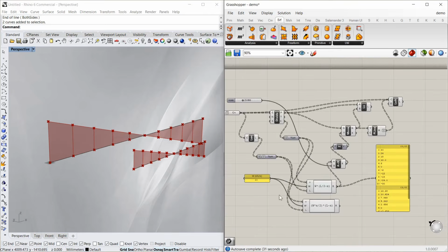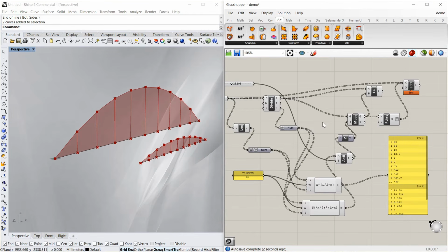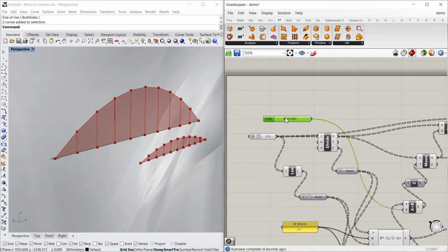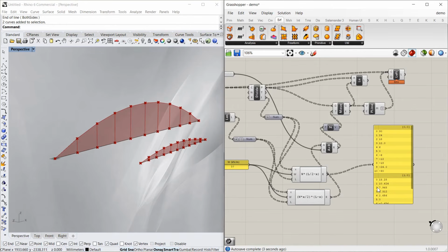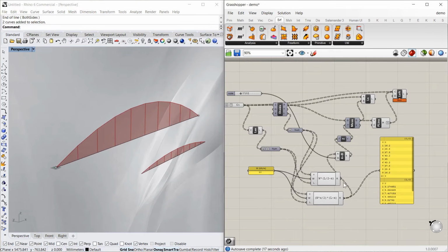So let's see what this gives us. There's your bending moment diagrams. And again, I can scale them as I need to, and I can see the results in this panel. In a minute, I'll put a result here so you can see it on the screen as well. I'm just going to turn off some of these points because I don't think we really need them. You can keep them if you want, but I'll just turn them off. So we've got our shear and our bending moment.